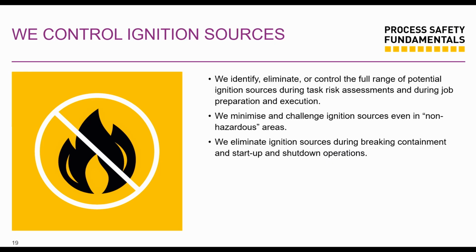So when you're breaking containment, you need to make sure that, sometimes you have people doing hot work in some other areas. Even if it has to be close by, maybe they need to build a containment, like a little shed, to make sure that all sparks are contained. There are so many ways. You need to make sure that cars that are passing, whatever vehicles you have in that area, can handle not releasing sparks that could cause ignition. So all this is controlling ignition sources. This is very, very key.